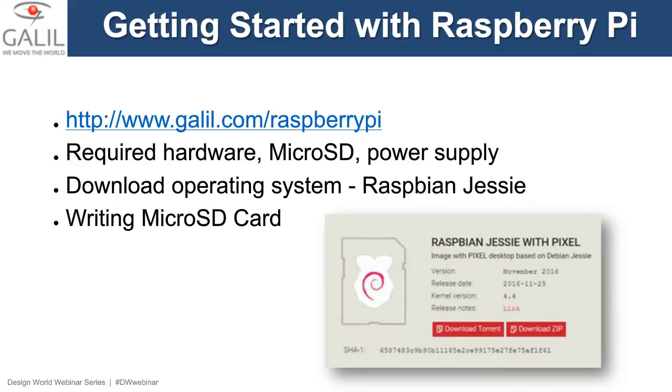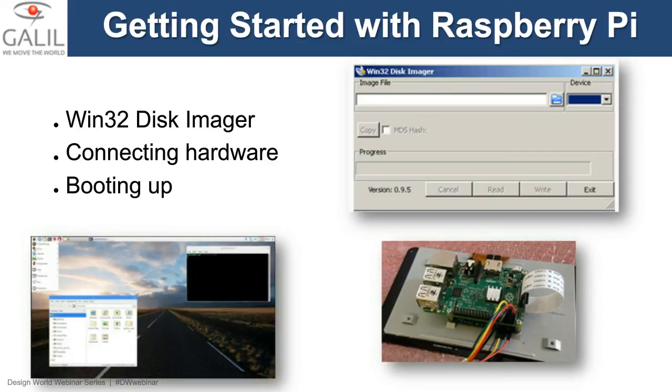There are actually a couple of specific programs that you can get to run in Windows, just to make it easy to load this operating system image onto the SD card. It's called Win32 Disk Imager. It's a free download. You can head over to their website and download it, and when you download the Raspberry Pi OS image, you select the image, select your micro SD card, click the write button, and now it's going to push this image onto this card and make it all ready to go.